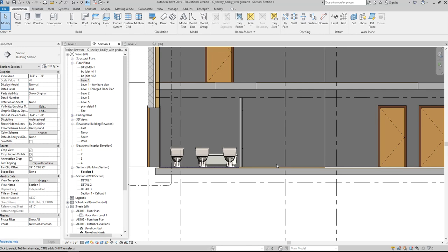Another way that we've done this, which is probably on equal footing with this way, and we're not going to learn this in this class because it's a little bit advanced, but another way of going about this would be to apply a color scheme to your floor. And a color scheme will allow a pattern to be read, but not give a thickness and apply a floor to it. So instead of showing an actual floor with a 1 inch thickness, I'm showing my structural floor, and then I'm essentially applying a hatch to it. So it's showing what it needs to show in floor plan view, but in sectional view, it doesn't show what it needs to show, right? And even though the flooring is just ever so slightly thick, I still think it's important to show it in section, so it's taken into account.